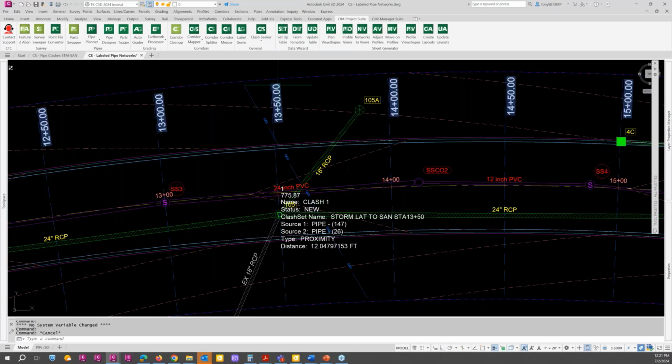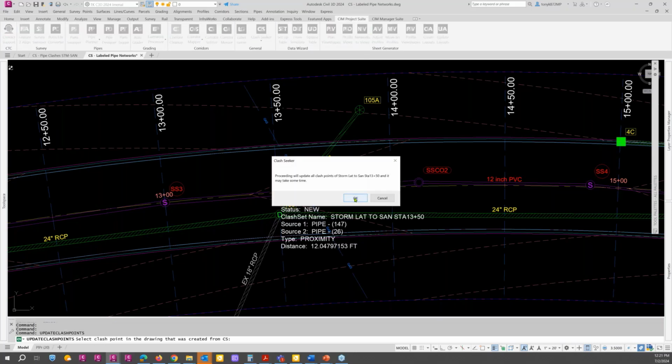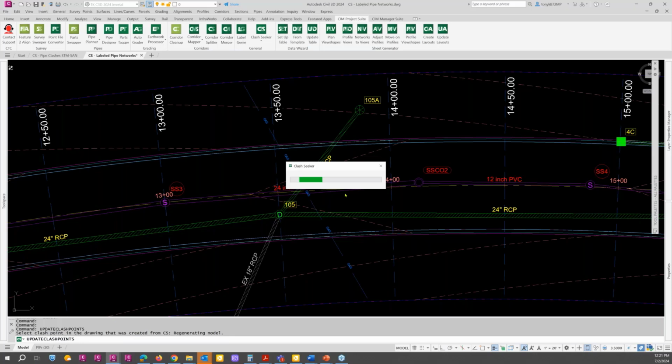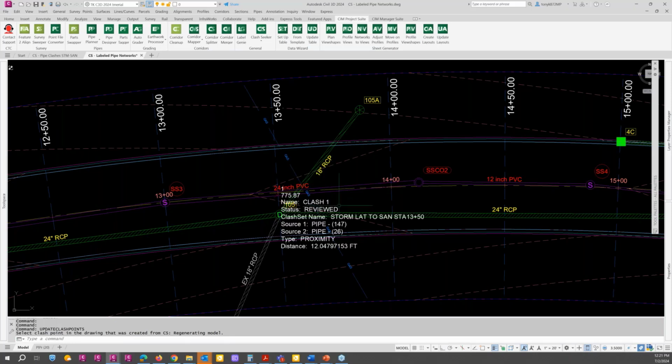If I updated that, so I resolved it, I can update the clash point. And now it says reviewed. So if you wanted to pick through these and clean them up, that would be the way to do it right there.